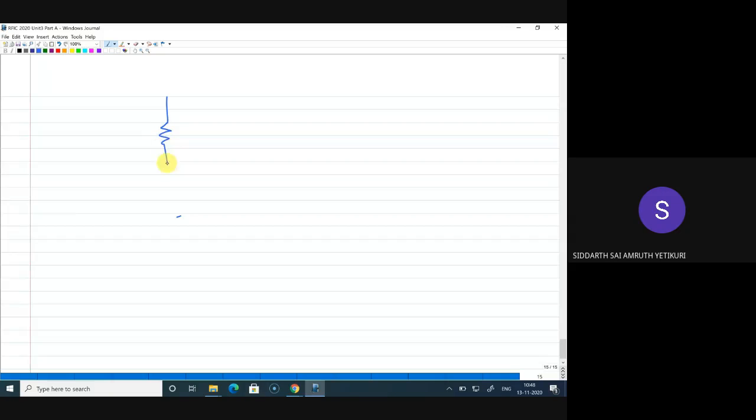So what if we place the capacitance in series and the inductance in parallel? All right, capacitance in series, you mean to say like this? Yes, sir. All right, put C in series and L in parallel. Okay, if I put C in series and an L parallel, definitely you will get an upward impedance transformation. Yes, that is true.